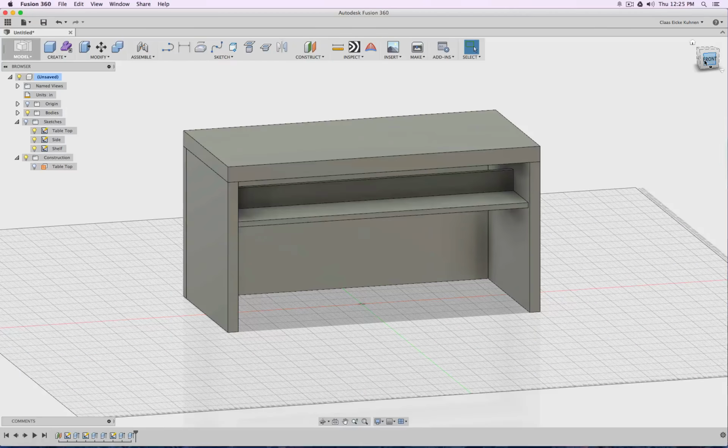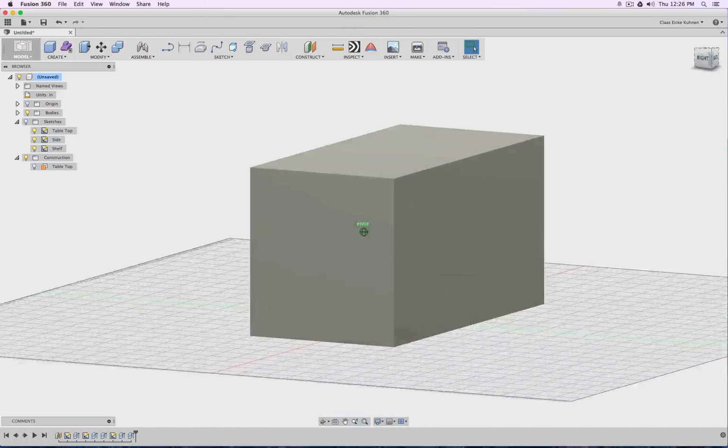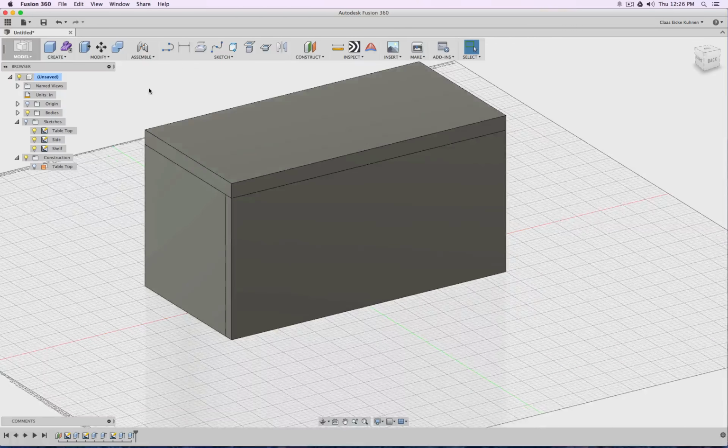Now, with the wooden table we did before, you want to really round these edges nicely, but here when we have veneer or something over it, it's not as possible to round it with a miter, because then you would just remove the veneer we glued onto the top, specifically in case the core is a particle board or something like this. So if we have small gaps in between, they have to be really very, very tiny.